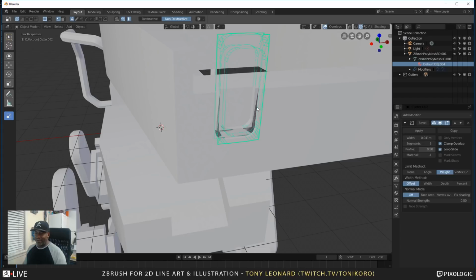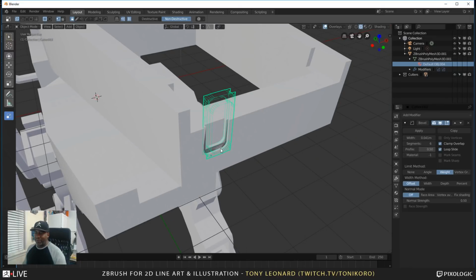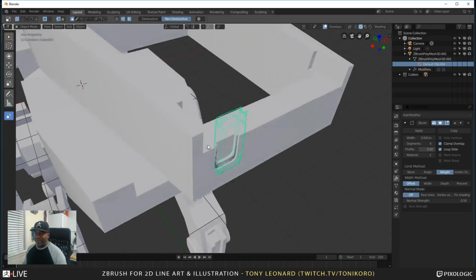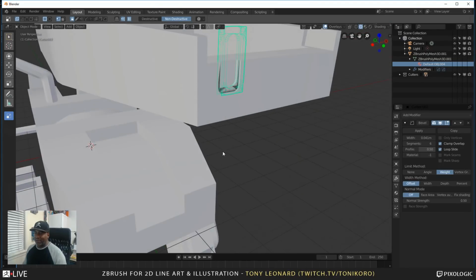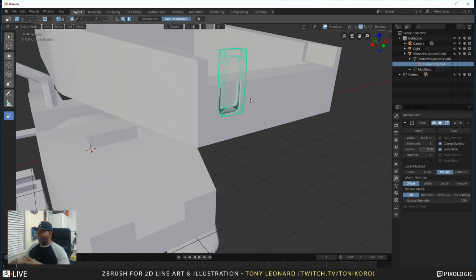The problem solving that's happening with this shading is probably the size and the way it's trying to solve cleaning up some faces, or what it's doing with some ngons. You might get some shading issues, so be prepared to come in and have to manage or close up certain faces. There is also a component called a blue box that you can use to cut between shapes like this and create a bisect in the object, and those bisects a lot of times will clean up a lot of the shading issues, because versus a lot of other applications, they don't know how to look at an actual